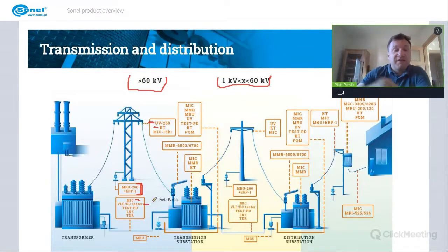So here it depends what types of cables there are under the ground. Generally, the high-pot DC tester is for the ones in paper insulation, and with VLF we can check the strength of insulation of cables, for example, in polymer PVC insulation.